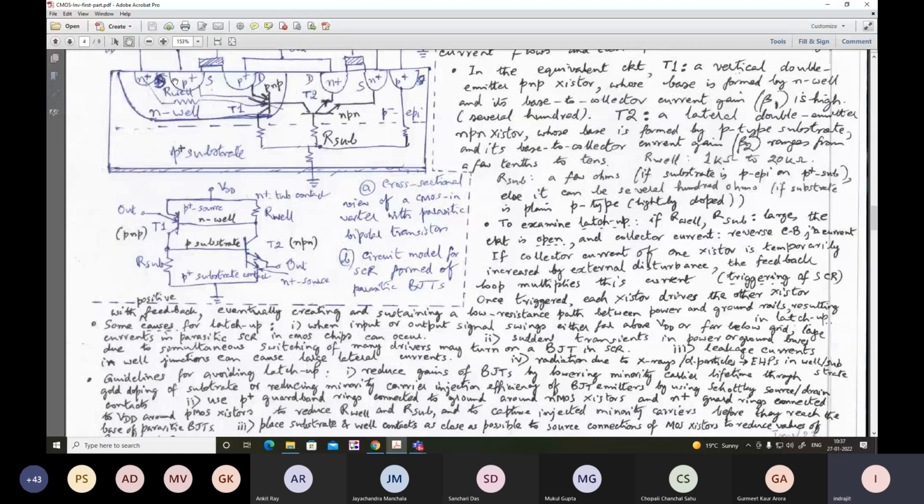Whereas in a field effect device, two simultaneous voltages, lateral and vertical, cause the current flow. But the current effect is more prominent in a BJT. So when carriers are emitted from the emitter into the base region, there should be less recombination and more should be collected. But in such a lateral device, what I guess is that the base is quite wide. And if it is wide, then a lot of recombination takes place and most of the carriers lose their existence. Very few carriers can find place in the collector. So the base to collector current gain is limited.